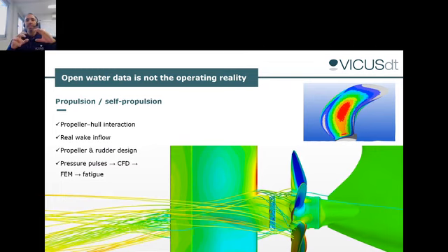And the very interesting one is regarding the cavitation and the pressure pulses. So the cavitation can be very accurately predicted, and you can squeeze the performance of the propeller, taking out the most of it. So it's very efficient, but at the same time, you stay on the safe side with the cavitation, which can be a big headache.